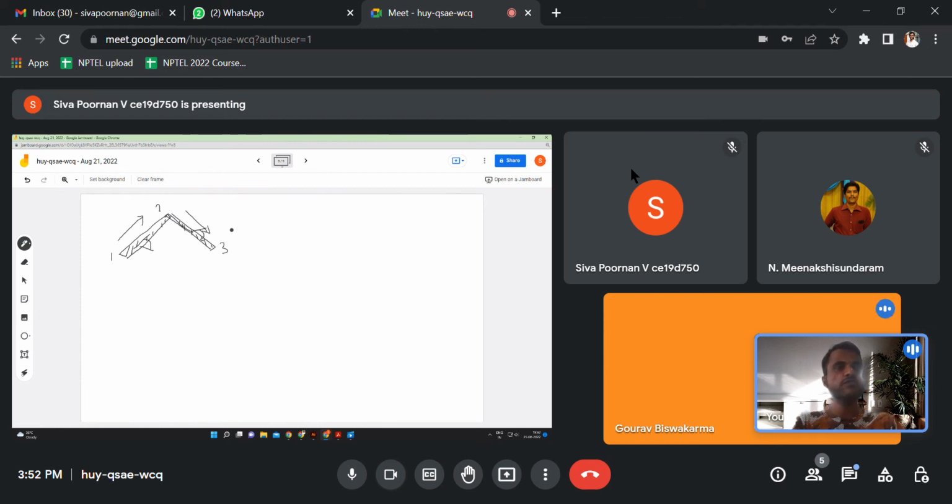What do we use? We use a condition on the displacement degrees of freedom. We would first be finding out the stiffness matrix of these two members independently, right? So we will say this is u1, u2, u3, u4, right? And if you do it for the second one, you will have u3, u4, u5, u6.